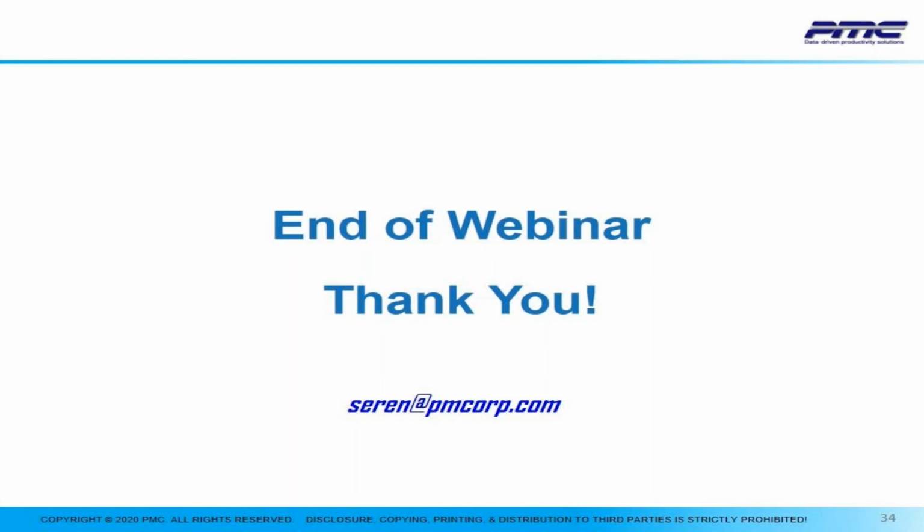And then we focus on the process. So I'll say 90% of the time you're not going to want to work on PFMEA first. You want to make sure that your product risks are identified and assessed before you start focusing on your process.